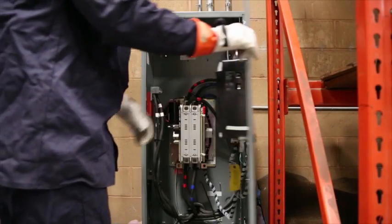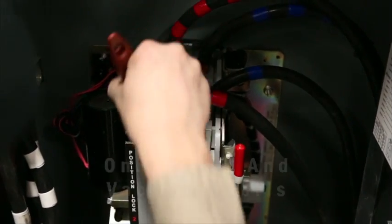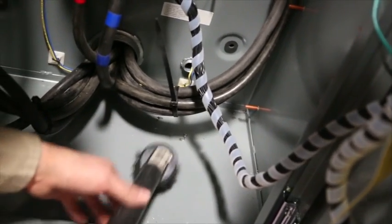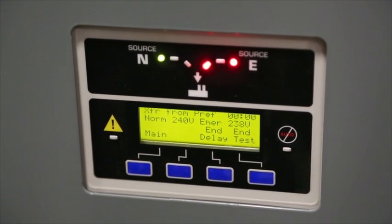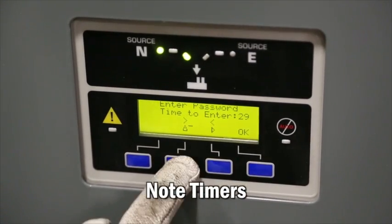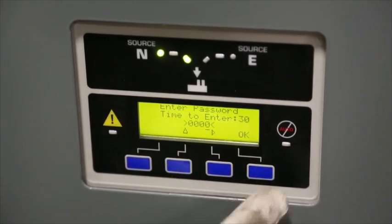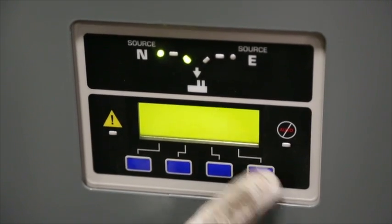During an ATS planned maintenance service call, the technician will brush and vacuum any dirt or debris from inside and outside of the ATS, and never use compressed air to remove dirt or dust. Check the operation of the transfer switch before beginning service. Check timers controlling the time for transferring to the standby power supply and the time before returning power to the utility. This avoids several transfers when power is going on and off or only interrupted for a short period.